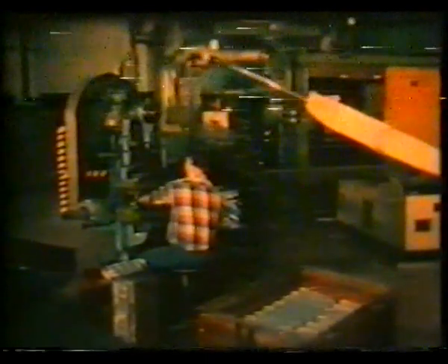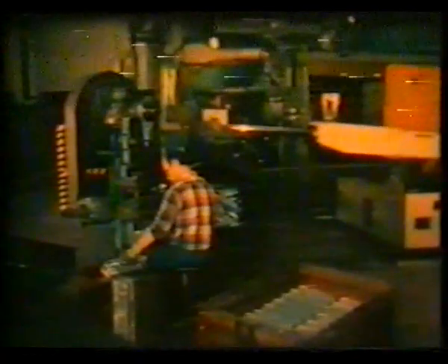Taking a few plants as examples, we would like to show you how Buhler die casting machines are used by our customers. This, for instance, is a plant for the automatic production of carriers for bicycles. The shot weight is 0.6 kilogram with 120 shots per hour. After trimming, the castings are polished and assembled into carriers.